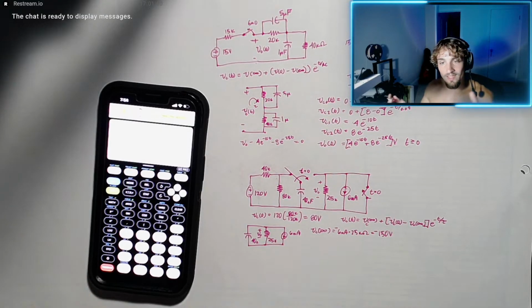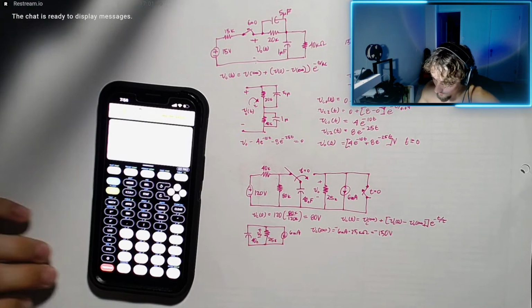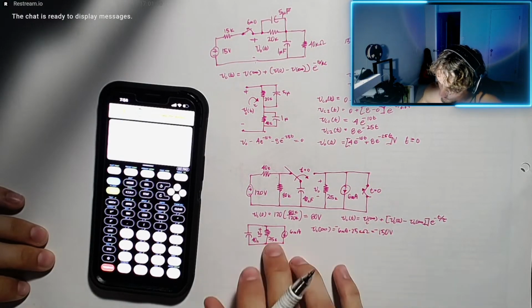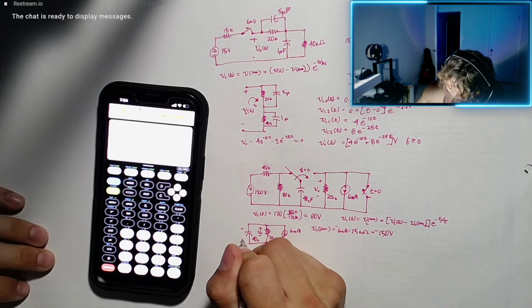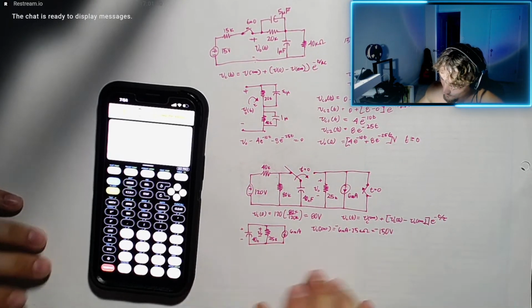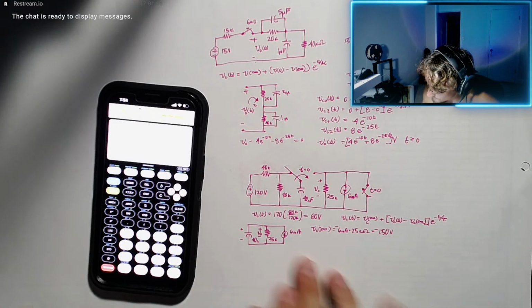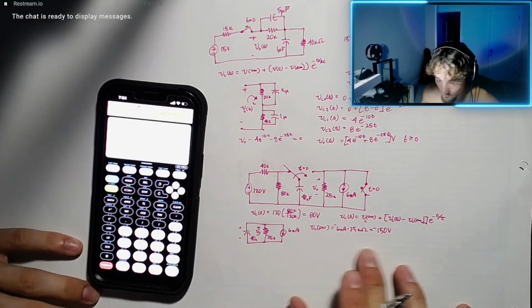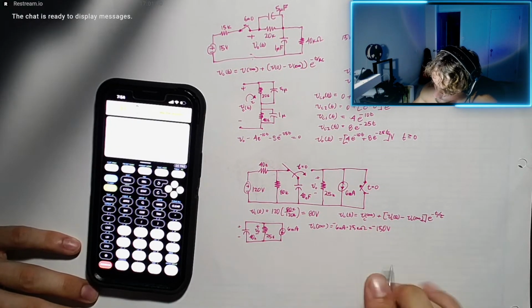Negative, because we can only have a voltage drop across the resistor, correct? If this current is flowing in this direction, that makes this the positive side and that the negative side. In comparison, if we're looking at the capacitor, it's positive, negative like that. Therefore, it would be a negative voltage drop across it, essentially a voltage rise in reference. Anyways, now we've decided that, so let's plug this into the equation.